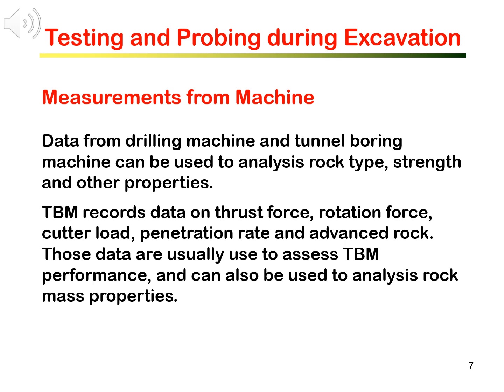For example, TBM thrust force, cutter load, and the penetration rate result from rock strength or hardness. Once such correlation is established, it is possible to use machine monitoring and the performance data to estimate rock mass and the ground properties and the conditions.